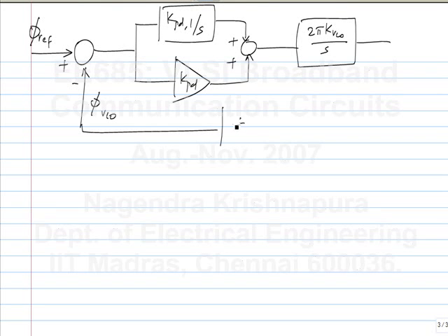And the exact same calculation will hold for the linear phase detector with data. Okay, the block diagram is the same, so anything you evaluate here is the same. Only difference in the block diagram is this n is 1 in case of the clock and data recovery circuit typically. The VCO will be at the same frequency as the data. There won't be any division in the feedback.